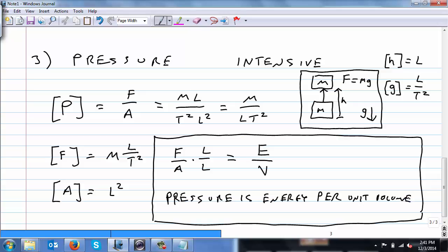And we did a little bit of that in the practicum last year. We bought an air compressor and said, okay, how can you store energy? Well, you can jack up the pressure inside your air tank. And, well, how much do you have? Well, multiply the pressure times the volume, and that's how much energy you have. It's kind of wimpy. It's not very dense, but if you've got an abandoned salt mine somewhere, you could conceivably put a lot of air down there in a big volume, and with relatively small pressure change, you might store some energy. Okay, pressure is energy per unit volume.